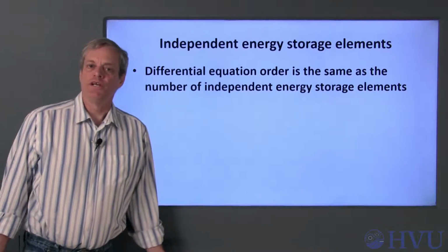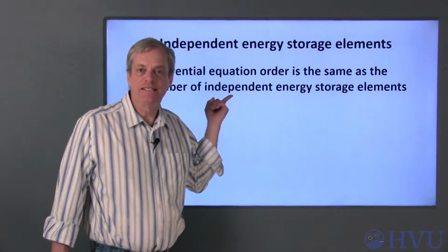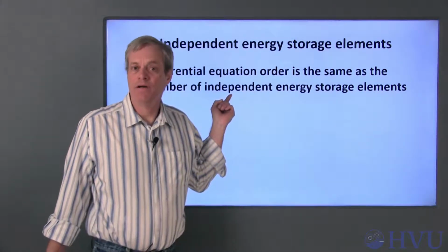As with resistors, energy storage elements can be combined to form a single equivalent energy storage element. In this video, I'll show how to combine capacitors to form an equivalent capacitance and how to combine inductors to create an equivalent inductance. The order of the differential equation describing a system is the same as the number of independent energy storage elements in the system.